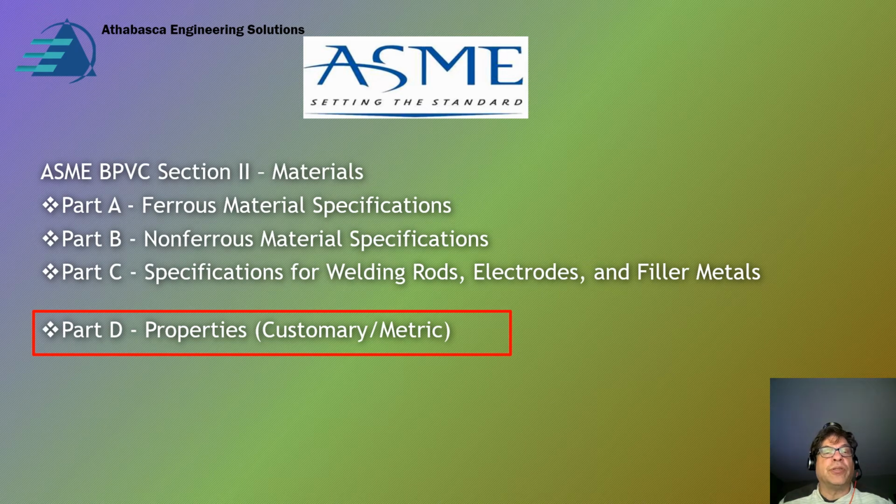Section 2 is pretty interesting. You have Part A, which is ferrous materials like your irons and your steels, and then your non-ferrous alloys like your Inconels would be Part B. What you'll see is that these are the listed materials, and they borrow pretty much everything from ASTM. For example, you have A516 plate.